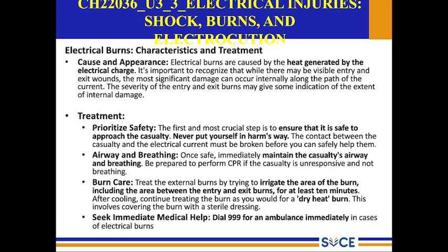Burn care. Treat the external burn by irrigating the area of the burn, including the area between the entry and exit burns, for at least 10 minutes. After cooling, continue treating the burn as a normal dry heat burn, where blisters will not be there. This involves covering the burn with a sterile dressing. Seek immediate medical help. Dial the emergency number for an ambulance immediately in case of electric burns.